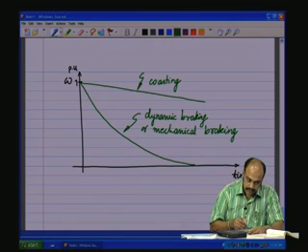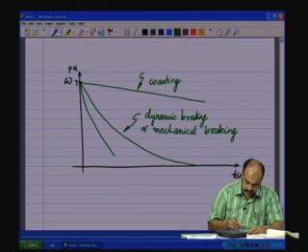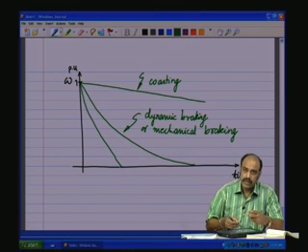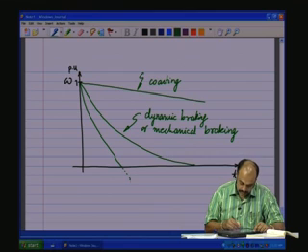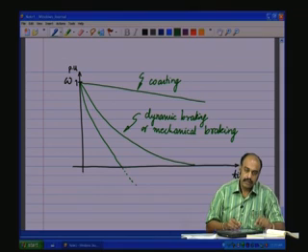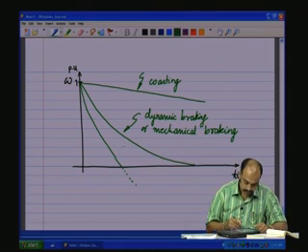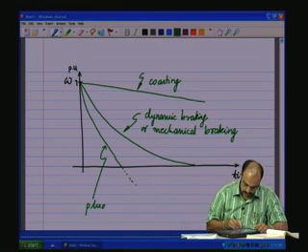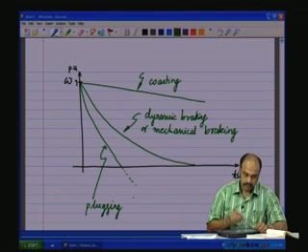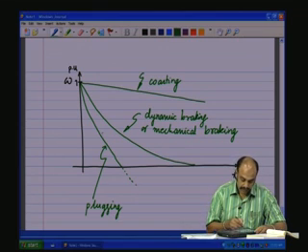Then the third one would be the plugging, and that would be very fast, and you should see that it comes to 0. After it comes to 0, because you are applying EP in the reverse direction, it will try to change polarity and start rotating in the reverse direction, but you have to switch off at the point when omega becomes 0. So, this would be plugging. So, plugging would be the fastest.